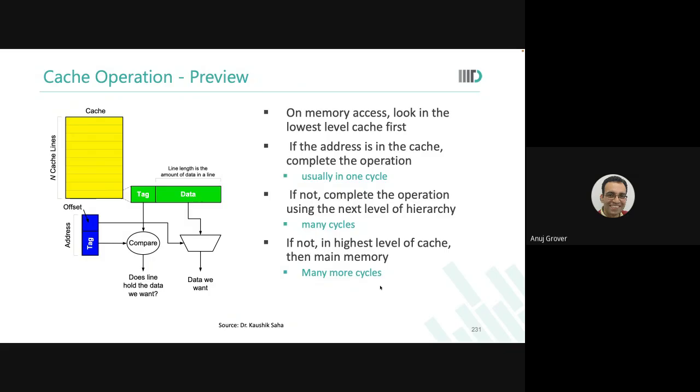Are you able to see this? Is this broad level concept clear? That you cannot store every location of the main memory in your cache. What you do is, even though your processor is 32-bit, your cache may be larger than 32 bits, or there may be a cache which is the data memory and a tag memory. Tag stores the remaining 22 bits of the address.